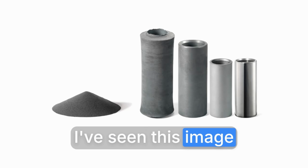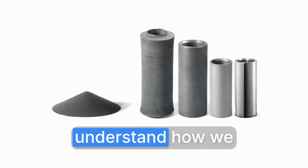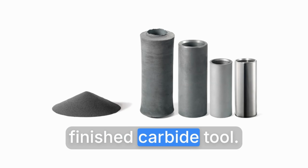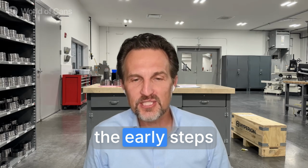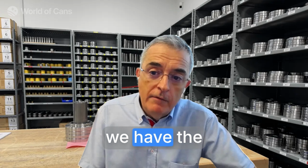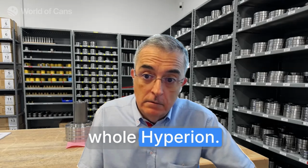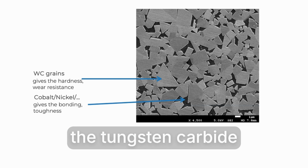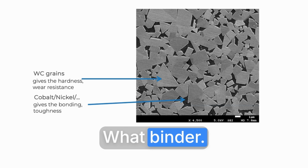I've seen this image from Hyperion many times, and we want to be able to understand how we get from this powder all the way to the finished carbide tool. Can you walk me through some of the early steps when we deal with developing the alloy? Here in Barcelona, we have the R&D laboratory that develops carbide grades for whole Hyperion. The first thing you have to do is design the grade, design the material, design the grain size of the tungsten carbide we are going to use, what tungsten carbide, what hard face, what binder, how much binder.